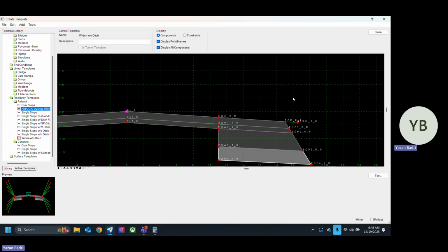The existing pavement goes like this, so when I say based on, is it reading the existing pavement and doing 11 from the center? We found the existing center line, right? Right. So then we're going 11 feet and saying this is where the saw cut line is. So we're just gonna cut the pavement there and then add the widening next to it. If there's more pavement on it, it's gonna get cut out. If it's like 13 feet from the center line to the edge of the existing, we're gonna have to cut 2 feet.